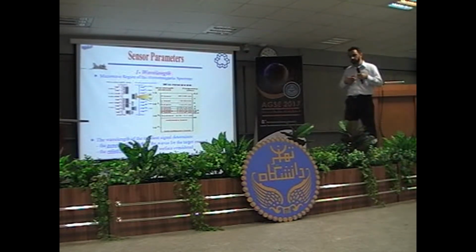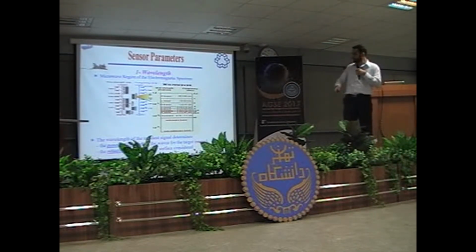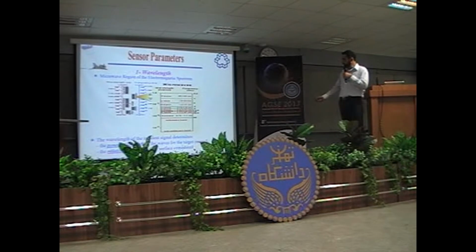X-band satellites like TerraSAR, the German satellite, work in this range, about 3 centimeters. After X-band, we have C-band. C-band wavelength is about 5 centimeters, and the main example here could be RADARSAT images. The Canadian RADARSAT images are C-band. Another popular example is L-band, where the wavelength is higher, about 20 centimeters or so. The example here could be ALOS images. ALOS is a Japanese satellite.